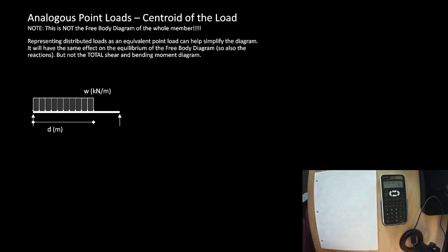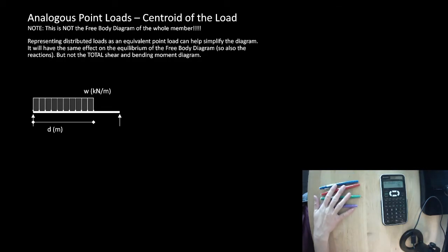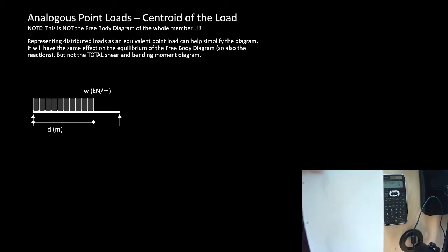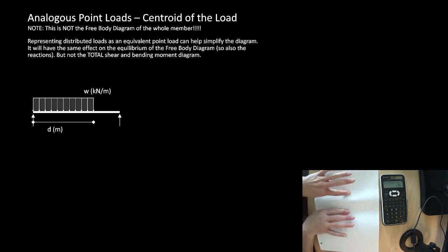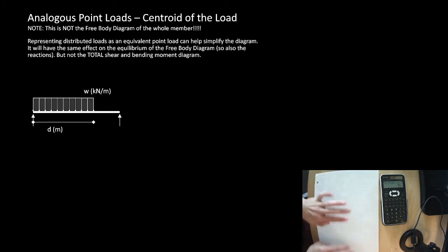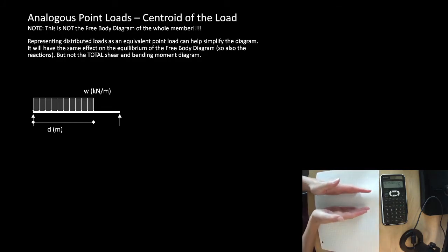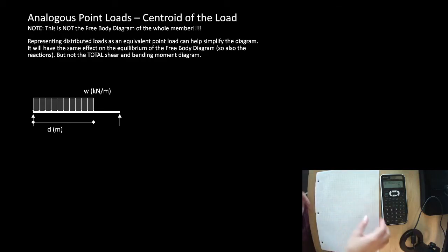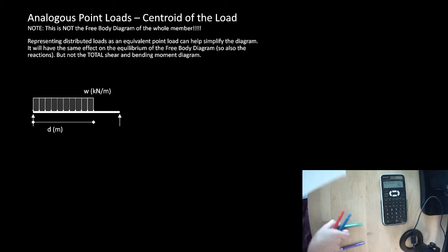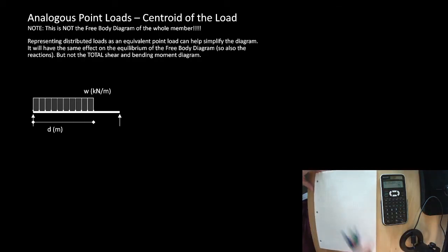Remember, here's a good way to show it. I've got a series of pens here, and I set this paper down on it. Each one of these pens is picking up half of the distance on each side of them. So this pen right here is picking up all of this piece of paper. So everywhere along its length, it's picking up a tiny little bit of load until it gets all the way to the end. That is a uniformly distributed load.